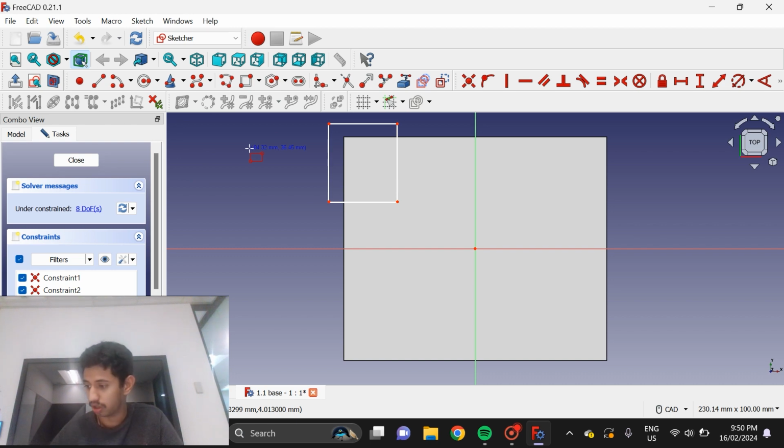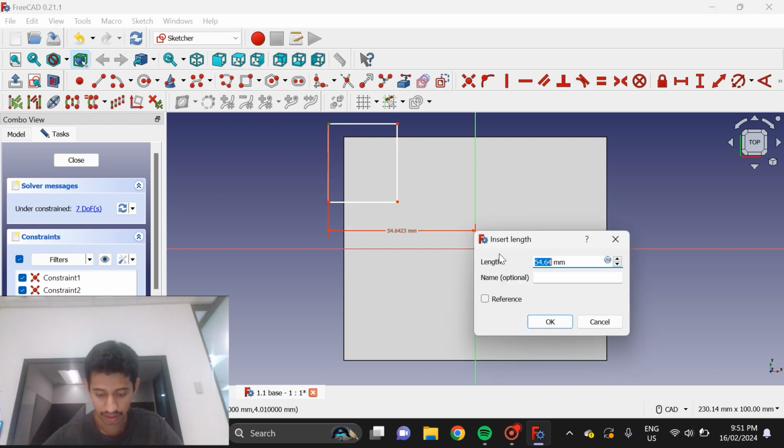So we'll work on the outside rectangle first, which is this one. So A, B, D, C. First we need the constraint of A. So we'll start with the horizontal constraints, and we'll start with A. I'll take this to this. Now A, X, it was calculated. It should be, yes, A, X was 63.85.